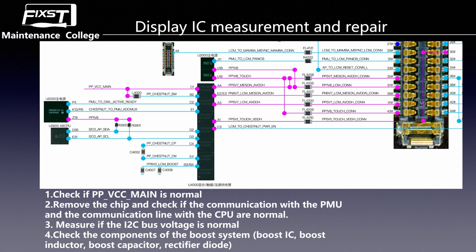For the display power IC to send the normal power, the display power IC alone is not enough. It also needs a booster system. This booster system has the booster IC, booster inductor, booster capacitor, and the diode. But the diode is integrated in the IC.